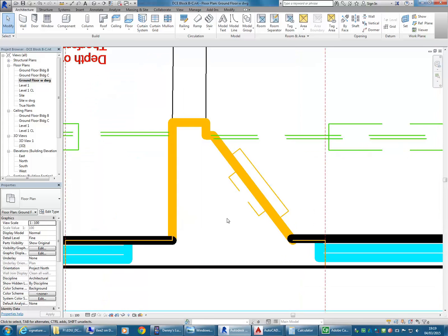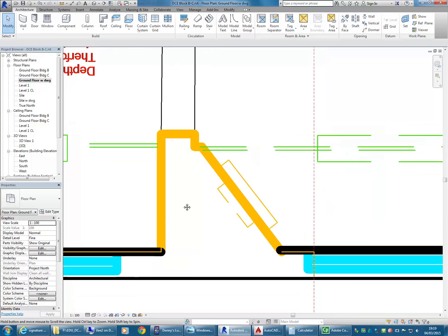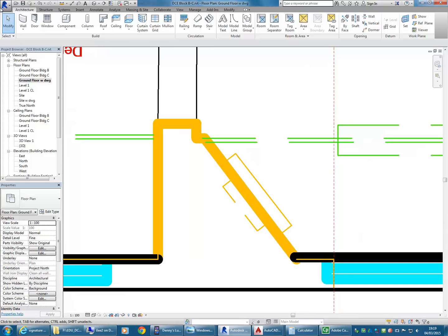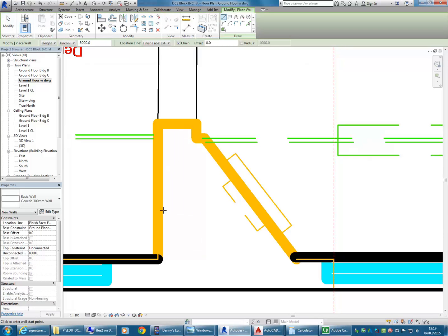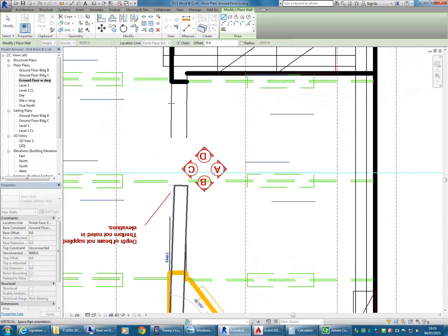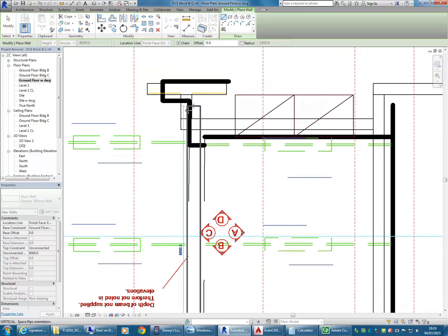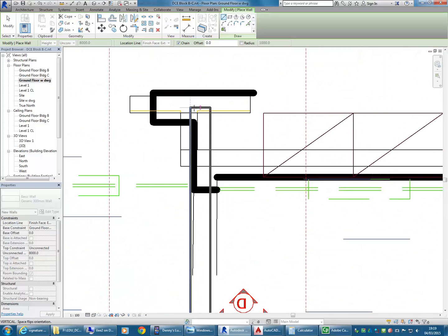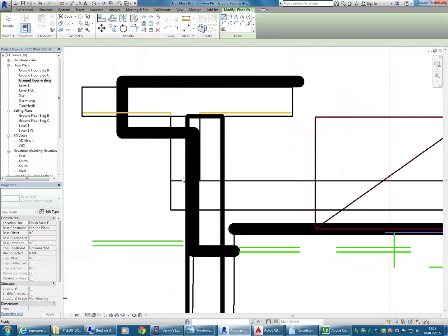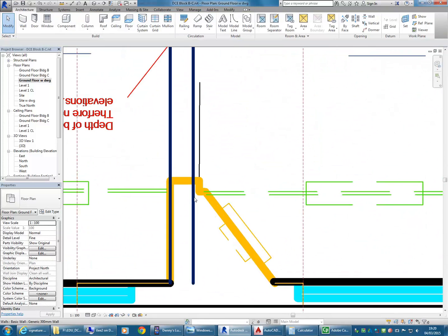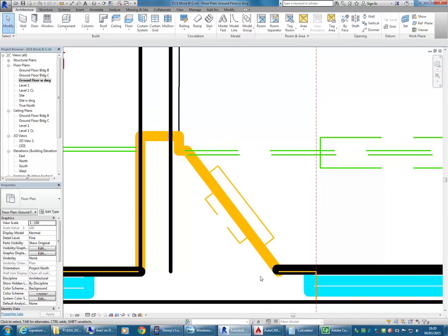So then the final thing I was going to say is to model, I think, something like the mantelpiece. Would you know how to do that? This mantelpiece, which is that triangular shape, a simple way, so you could model it with walls, and I'll just show you. If I draw a wall for the left-hand side, well, I've got some extra layers coming in there that actually shouldn't even be there. So I'll just draw this in pretty roughly for now. So I've drawn my 300 wall, which is at the back. But then this triangular part, you could use, again, just the wall tool to make that.